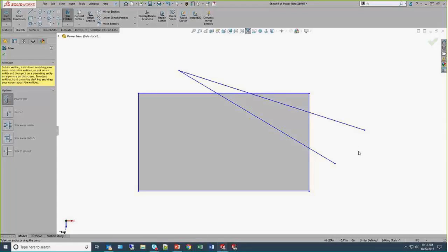And the way that it works is we just click and hold down the mouse. You can see that little line going across. Now, the hidden undo, notice that red dot. If you take your mouse back over that red dot, and I have not taken my finger off of the left mouse button yet, you'll bring that segment back. So it's a click and drag in order to get the trimming to work inside of power trim. Click and drag. And I could continue this process to clean it up.